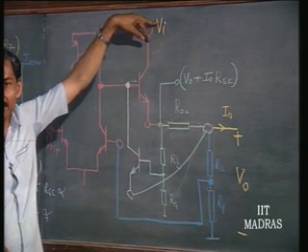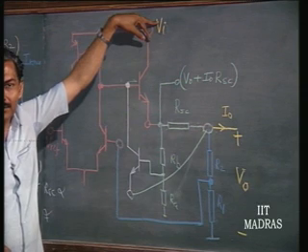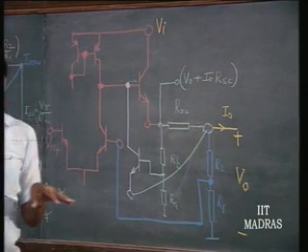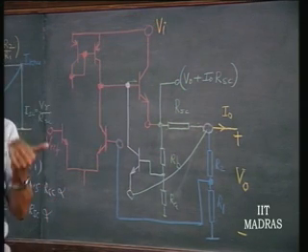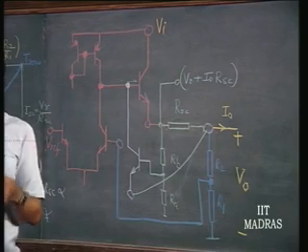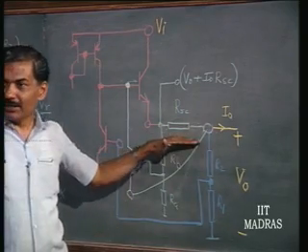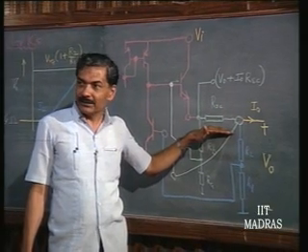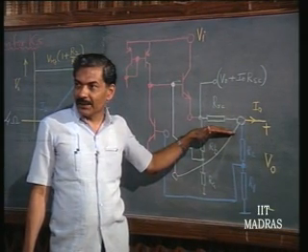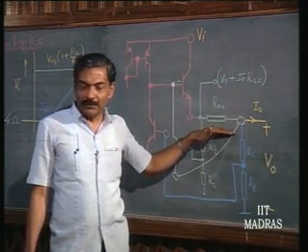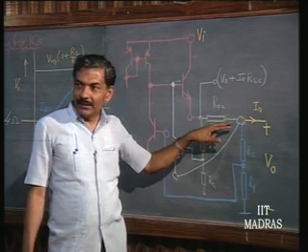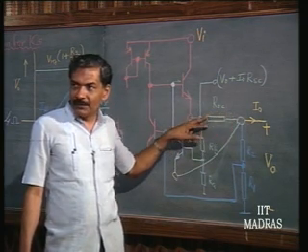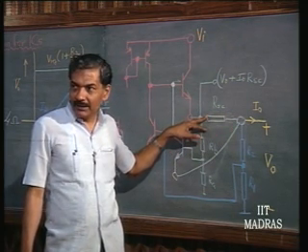The load regulation also will, yeah, apart from this, the output impedance, as he points out, is invariably going to be affected. Again these are all things which are going to be spoilt for our normal functioning, just in order to take care of short circuit protection. The output impedance, without feedback, is going to involve RSC straight away.